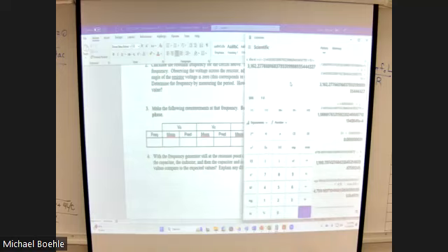That is the inductive reactance. You divide that by R, and that gives you the Q of the circuit. Now, the R in the circuit is a 1.2K ohm resistor, but what did we just say? Oh, there's another 100 ohms in my inductor. Oh, and there's another 100 ohms in my function generator. So the Q that I actually end up with is going to be that reactance divided by 1400.